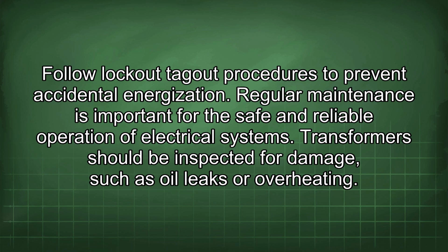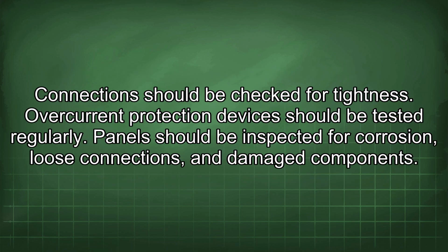Regular maintenance is important for the safe and reliable operation of electrical systems. Transformers should be inspected for damage such as oil leaks or overheating. Connections should be checked for tightness. Overcurrent protection devices should be tested regularly.